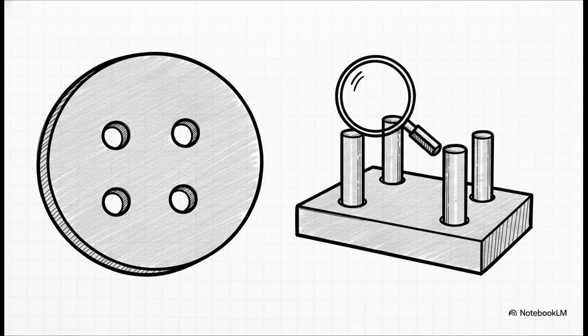The nominal hole is 15mm, with a really tight tolerance of plus 0.02. We've got a position tolerance of 0.2mm at MMC. So following our formula, the smallest hole is 15.0 minus that 0.2 position tolerance, which gives us a virtual condition of 14.8mm. Now, using our pessimistic absolute gauge tolerancing policy, we apply a positive tolerance only to the gauge. So we're going to machine our go gauge pins to be somewhere between 14.8 and 14.82mm.